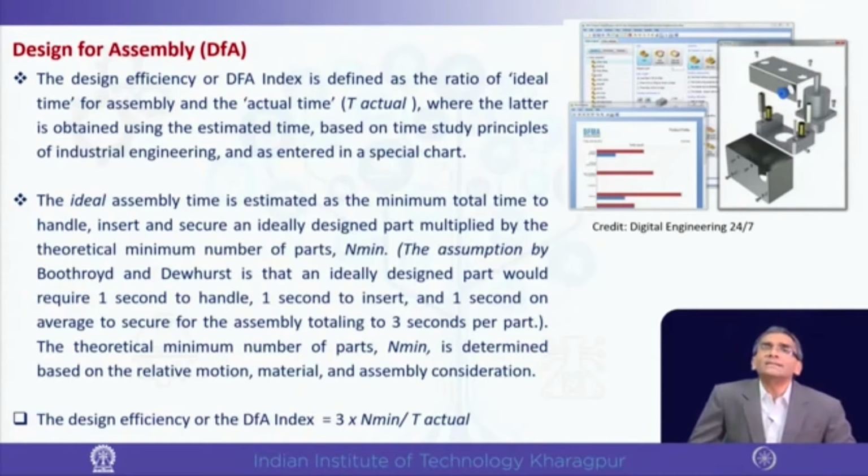It is considered to be the ratio of the ideal time of a product assembly, which is possible but actually not happening in reality, divided by the actual time. What is possible is a big question; while designing, there is a way to find out. The actual time comes from the number of parts and how much time each component requires to be assembled.